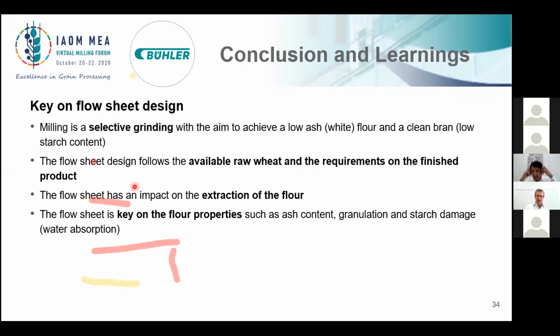So a purifier is needed for a purpose. It can be needed, of course, if you want to extract semolina. But it is also needed if you want to make a split flour, like a low ash patent flour, together with a baker's flour. But if you know from the very first day that it is running for 365 days on a straight run baker's flour, the purifier will not help a lot to give you higher extraction.